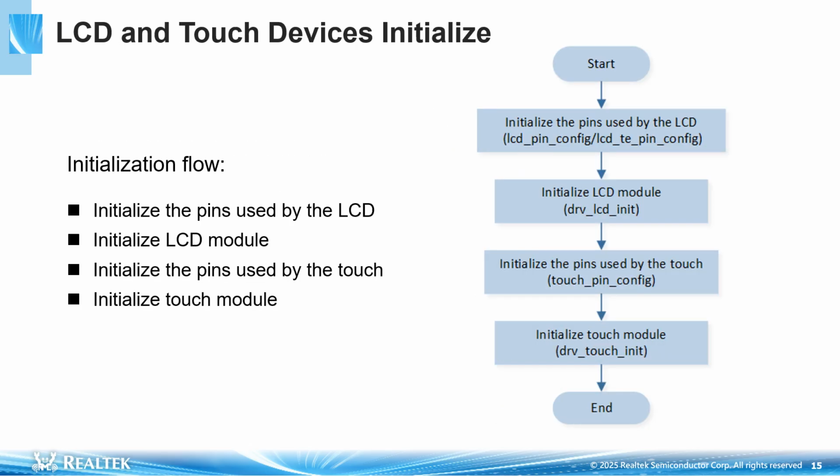Next, we will introduce the initialization of LCD and touch devices. First, configure the pins used by the LCD, then call the function drv_lcd_init to initialize the LCD. After that, configure the pins used by the touch device, and finally call the function drv_touch_init to initialize the touch device.